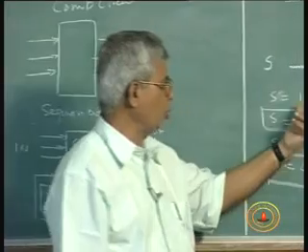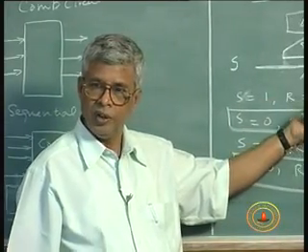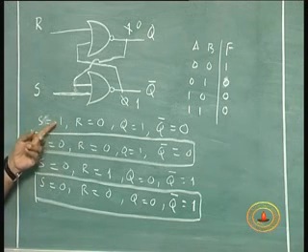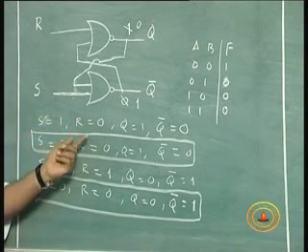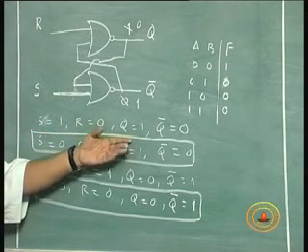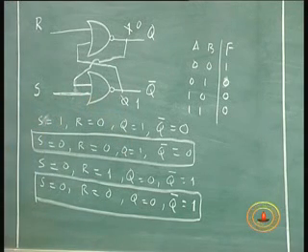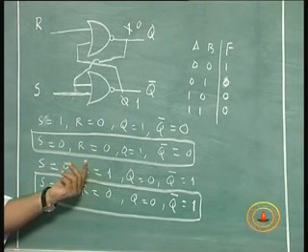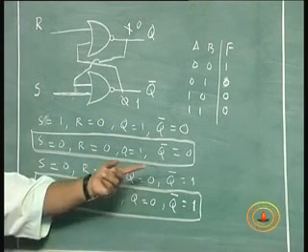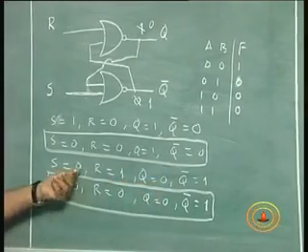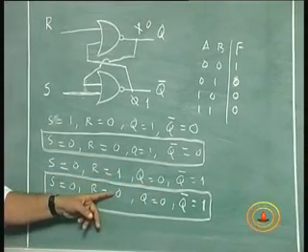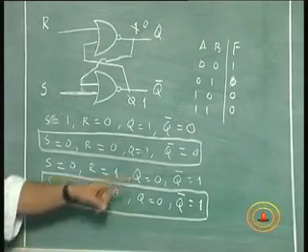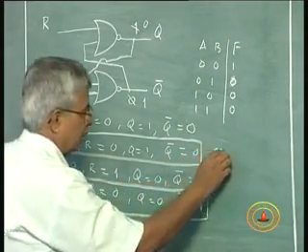So the information that was put was 1, 0, and after this, we removed that excitation which made it 1, 0, made it 0, 0, both inputs are 0, the output remained 1, it retained the memory. Memory retained the information 1, 0. Likewise, we put information 0, 1 and made the output 0, 1. After that, we removed this excitation of r is equal to 1, made it 0, output remained the same as previously, 0, 1. So this is a memory state.